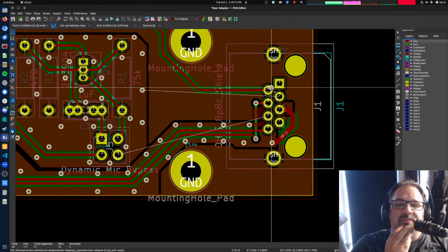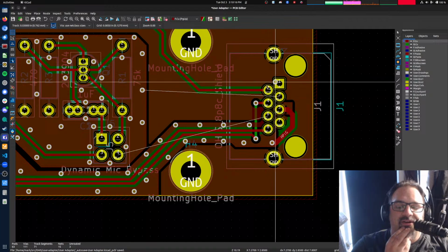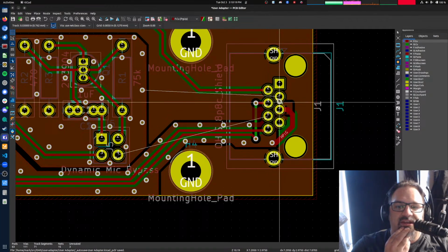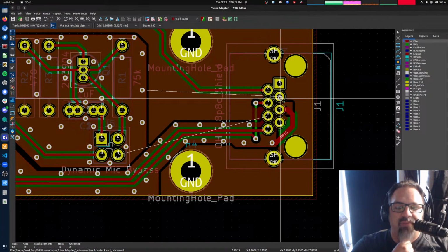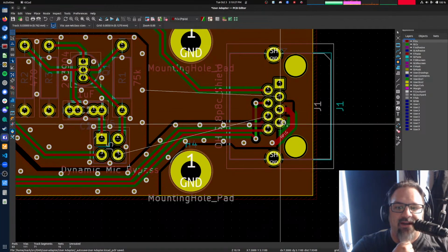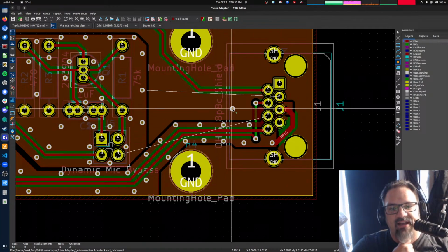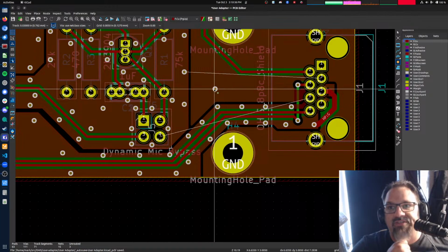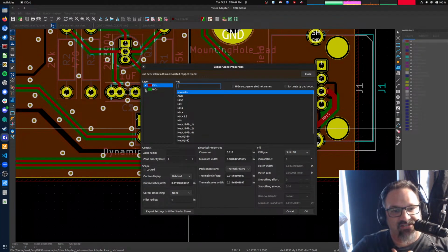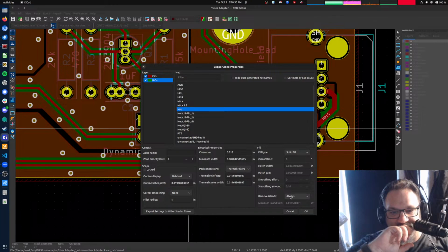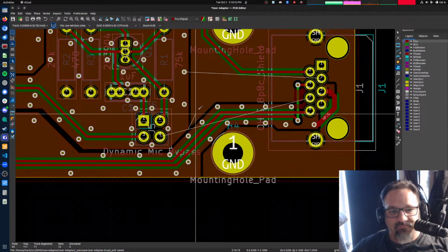If I were to do this, I would probably put the mic on the outside pair here and put the headphones in the four in the middle, and then probably pair it with PTT and then put power and ground on a pair out here. But I did kind of inherit this pinout from a previous document. I made some other changes from that document, so maybe I should have gone ahead and made that different, but here we are.